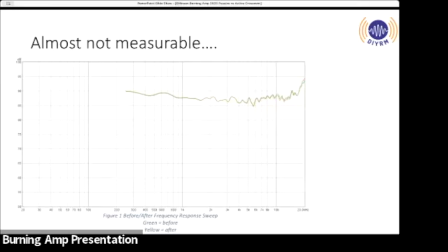That was half an hour. No, I mean, bipolar caps are notorious. And if they start off 10 microfarads on day one, by year one, they might be 7.5. Oh, they don't go that fast. They do not go that fast. Yeah, but the long term, I have measured 35-year-old bipolar caps out of speakers. If they don't have voltage on them all the time, they tend to be pretty good. Like I've measured many that still meet their original specs.